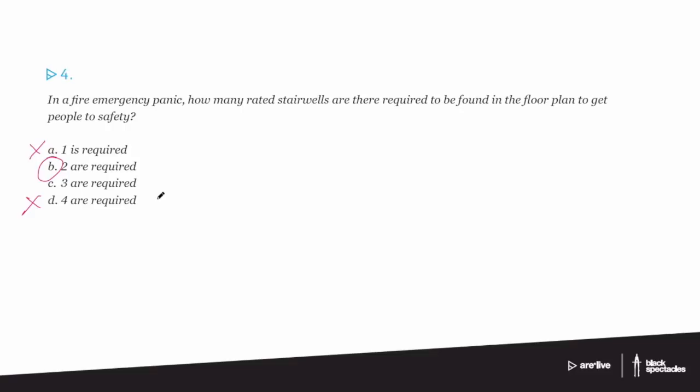In fact, even though the code is a gazillion pages long, you'll find that you keep going to the same pages. The occupancy count, the description of construction, the different relationships. If you're doing residential buildings, you look at the occupancy section about residential because there's a bunch of key pieces of information there. Out of all those 1,000 pages, you'll spend 90% of your time on 30 of them, and you actually start to get to know those pages pretty well.